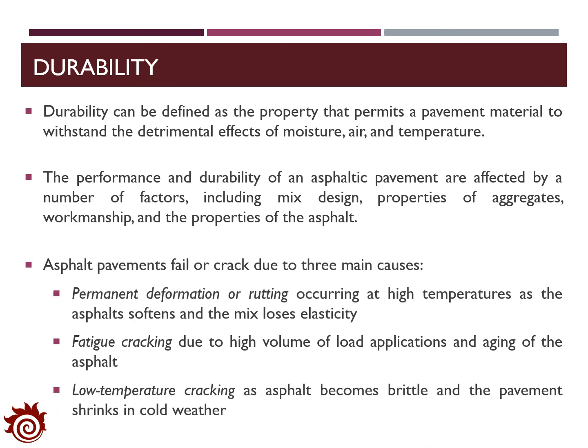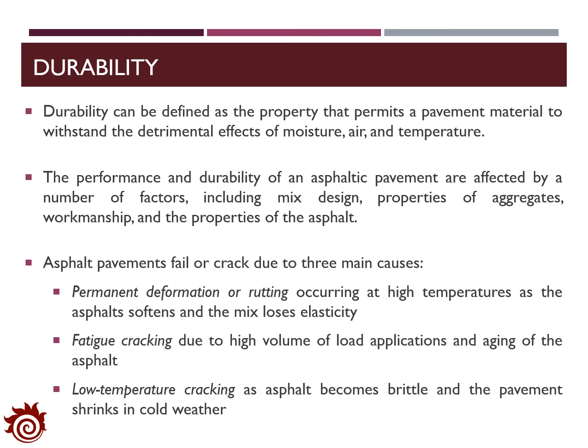In general, we can summarize three major causes of the failure of asphalt pavements. The first one is permanent deformation or rutting, which is caused by high temperature. At a high temperature the asphalt will become softer and the mix will lose elasticity.